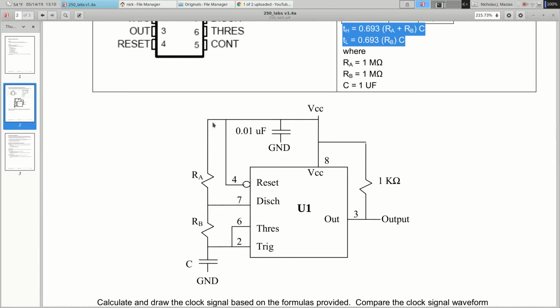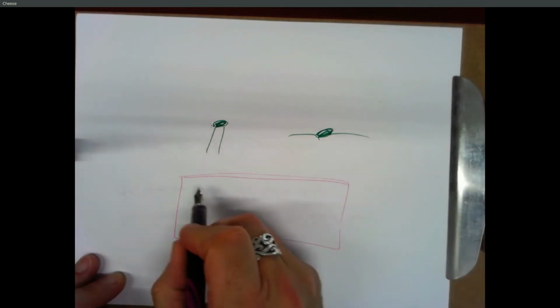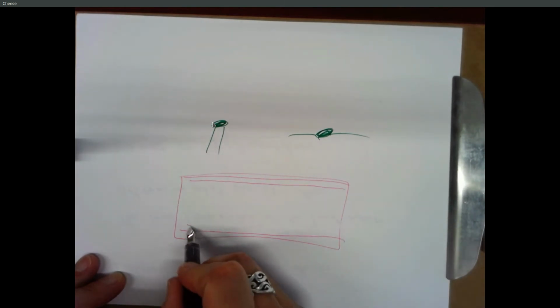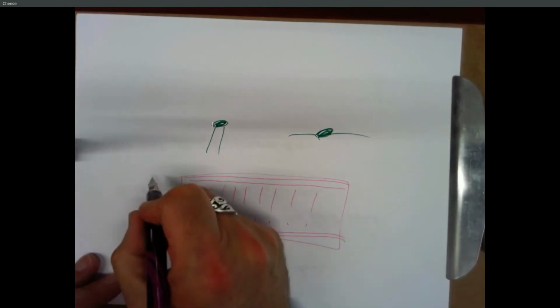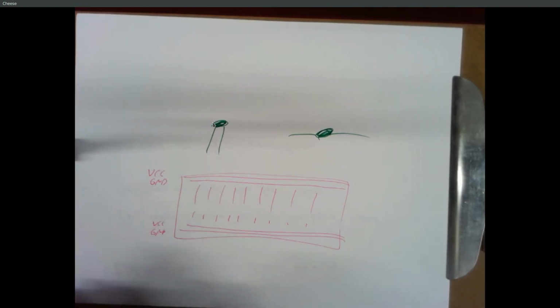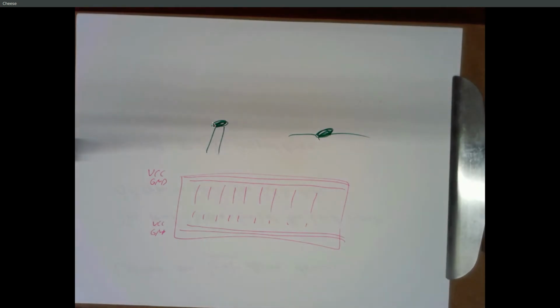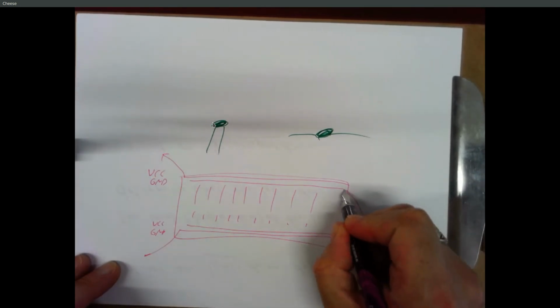Because you've got your VCC bus all the way across the top. And this is one case where it's worth it: on your proto board, you've got 2 lines on the top and 2 lines on the bottom, and then all these rows of 5 lines in the middle. It's worth doing VCC and ground on both sides. Usually there's a red and a blue, so pick something that makes sense to you. Usually red is VCC, blue or black or brown would be ground. But do something that makes sense. Connect one of these to your power supply, and then just put some jumpers on the other side.